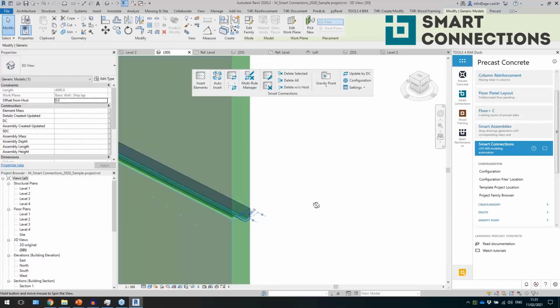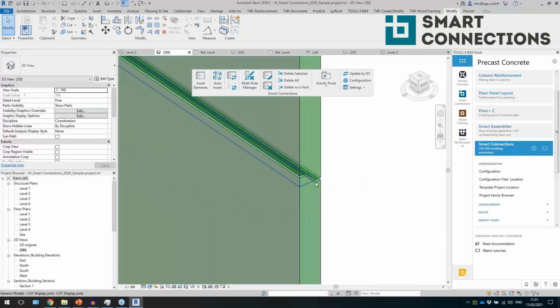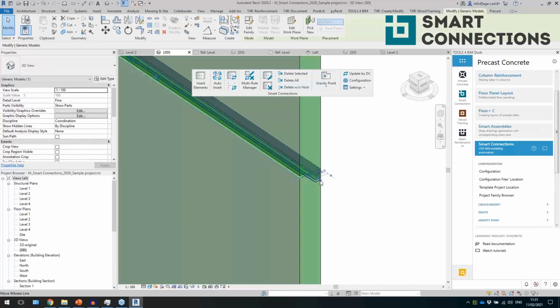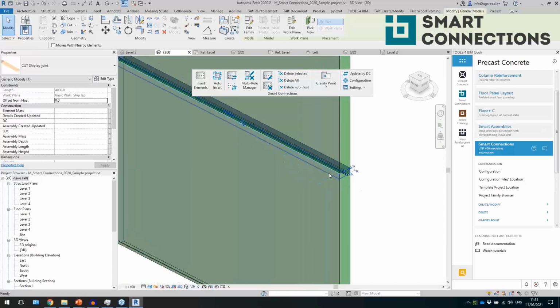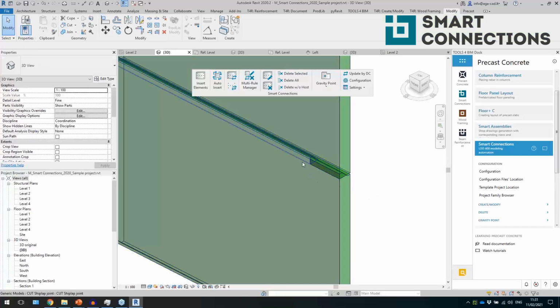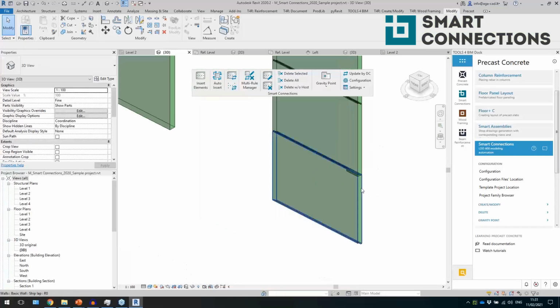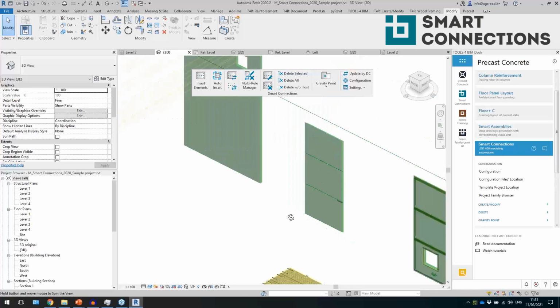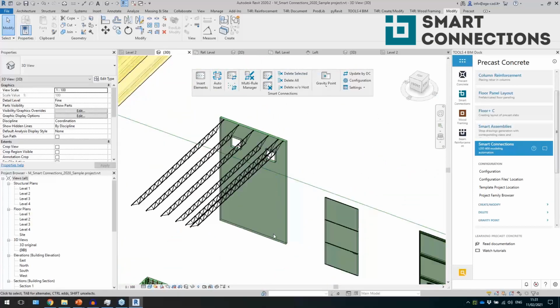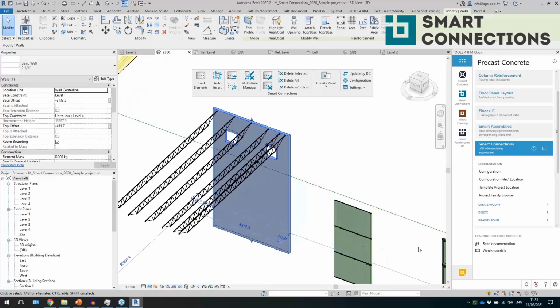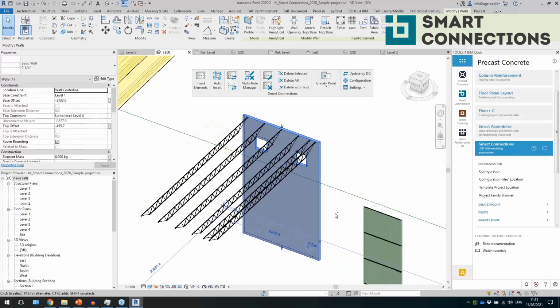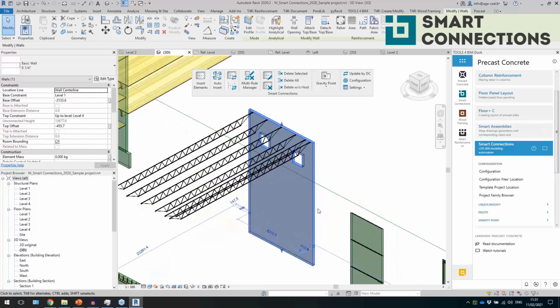This is also a shiplap joint, so I can place this kind of voids. You can do that with a Revit profile as well, but sometimes maybe you need to move something, change something, or maybe you need some quantity. In that case, line-based elements would be better than having profiles or sweeps inside the wall family. So that's probably the reason.